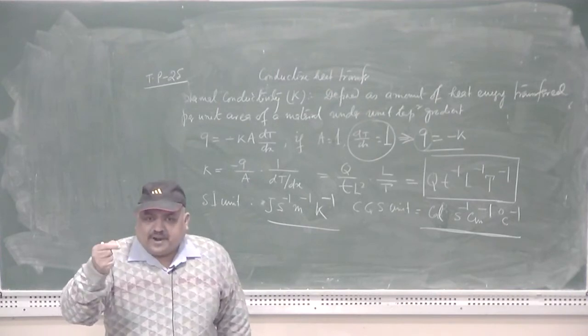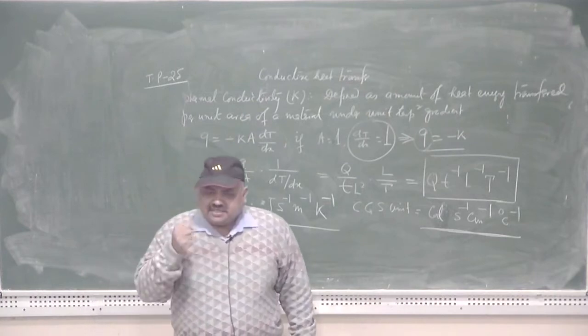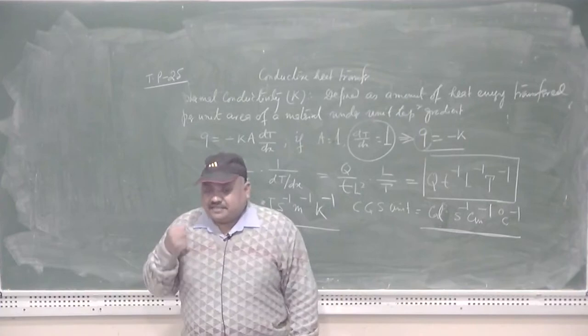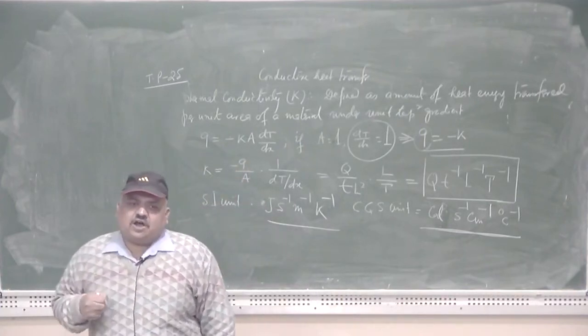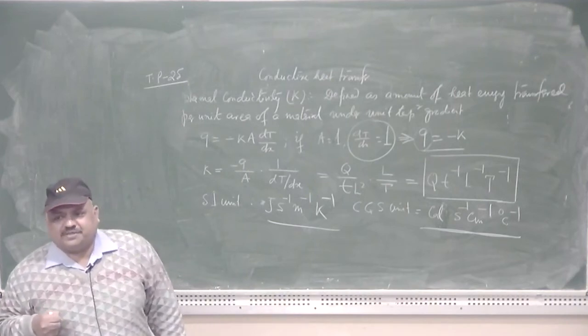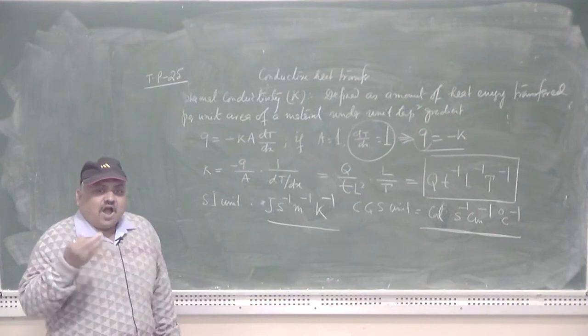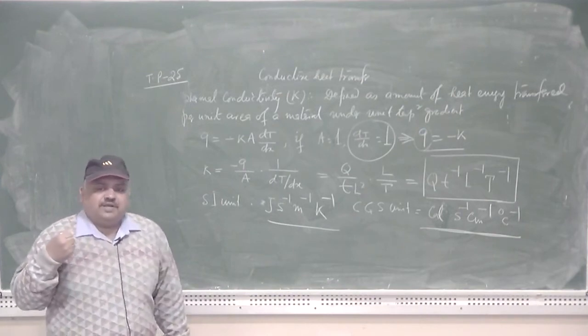Why? Because the thermal conductivity, the thermal diffusivity, and the specific heat capacity at constant pressure of the mold material influence how far the mold is able to absorb the heat energy of the liquid metal.